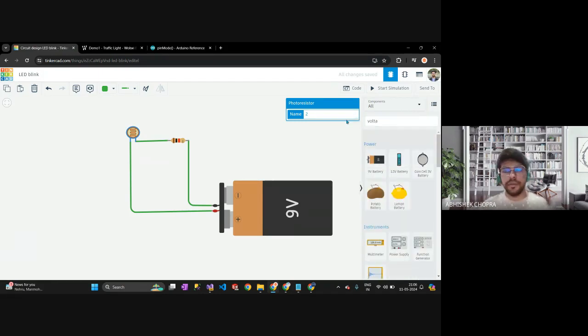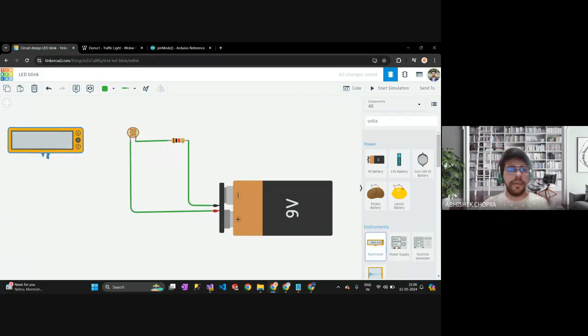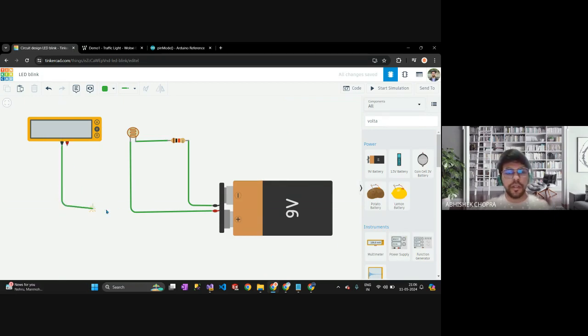Oh, sorry, my mistake. Multimeter only. Yeah. So in order to measure the voltage difference, I'll first connect the ground to the ground only, or we can say negative. The ground to ground is connected. Now, at what point do I want to measure? Since I want to measure at this point, the difference coming from this current is how much difference is from this point to this point, right? So I'll connect this point to the multimeter.